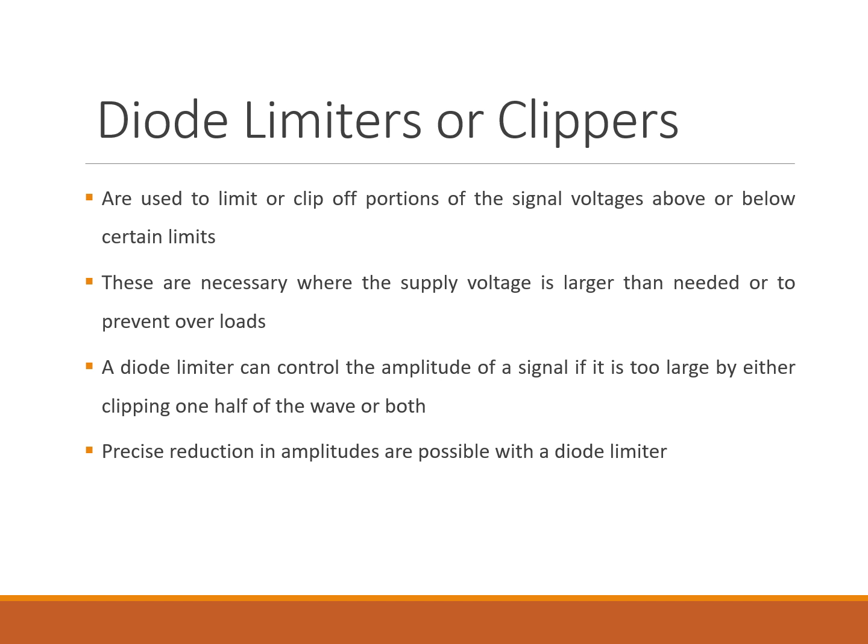And where do we use these? Well, we use these in audio processing, RF, and communication receivers. We can also use these for digital input protection, with analog sensors, and for waveform shaping. A good design tip before we move on is to always add a reference voltage to the diode to customize the clipping level precisely. And we'll see what that circuit looks like in a few slides.